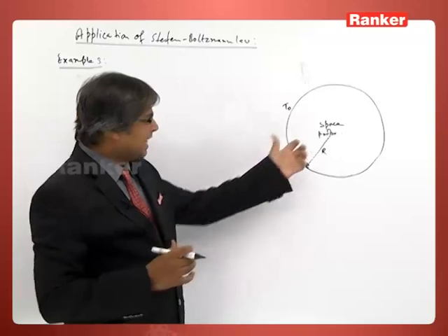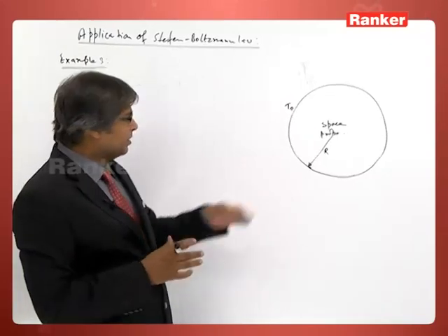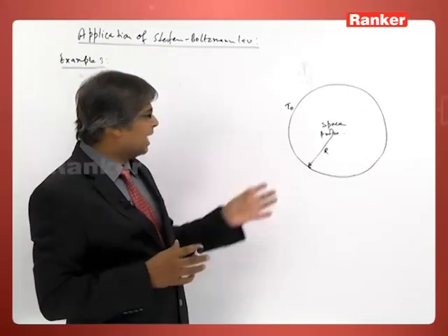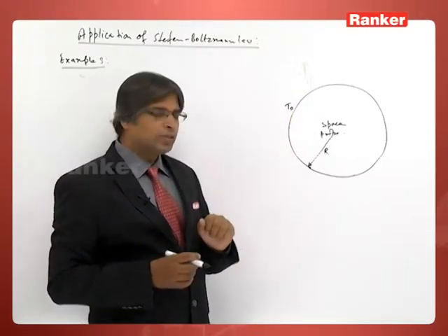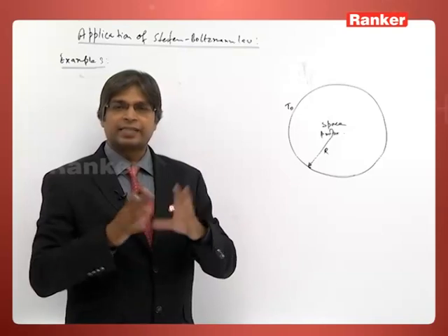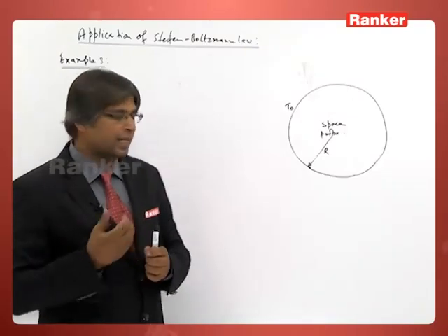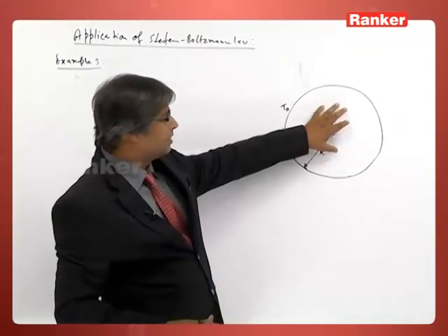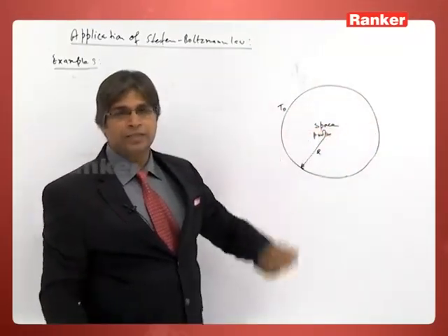So, now we have sent a deep spherical space probe for some long mission, and on the surface we have some electronic equipment, so that they will send radio signals and we can study what photographs they are giving and all such things. So, the electronic equipment must be heated so that they can work efficiently. They have some minimum temperature at which only they can work. So, if there are very cold conditions, they cannot work. So, inside this there is some nuclear matter preserved, which continuously produces heat and thus keeps this surface at a temperature T naught.